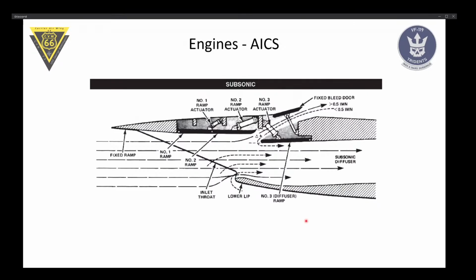You want to make sure that the air that enters your engine is well below supersonic, because as we have seen, the air that the airfoil sees is an addition of the circumferential velocity and the inlet velocity. Now at subsonic speeds, this is not a problem because first of all, part of the flow is taken out, and then we have this diffuser which increases the cross section, and this in turn reduces flow velocity.